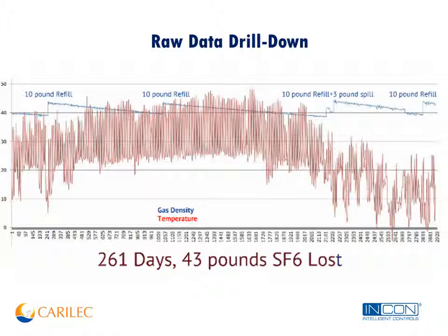One thing we notice right away is that it leaks slower during hot weather, and it leaks faster during cold weather. So this is a good diagnostic piece of information to know that it's likely a seal and not a casting problem. Seals tend to shrink and swell with temperature.